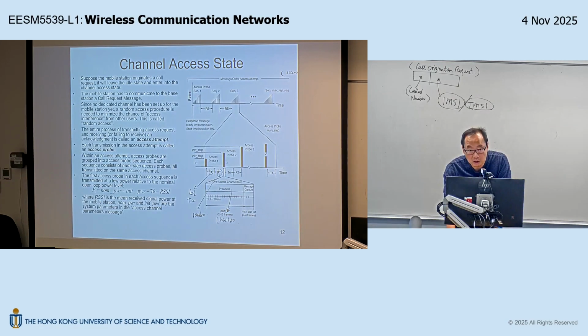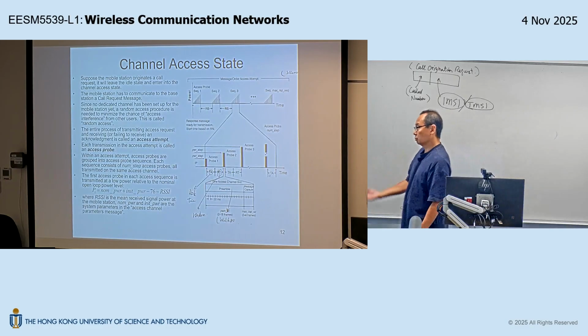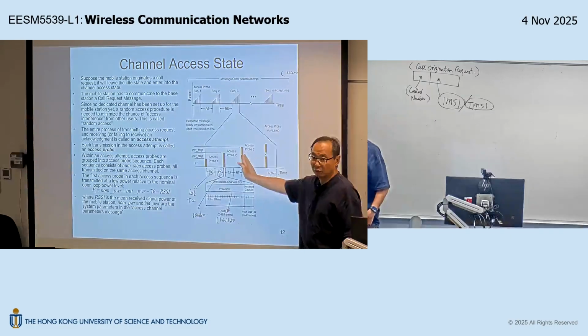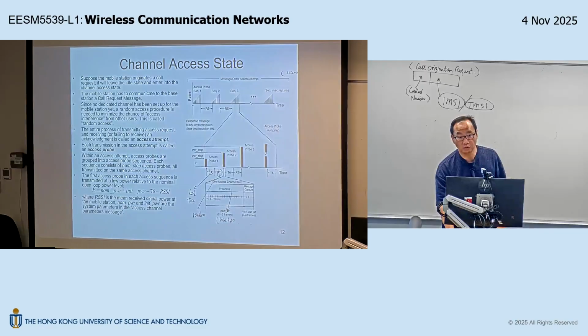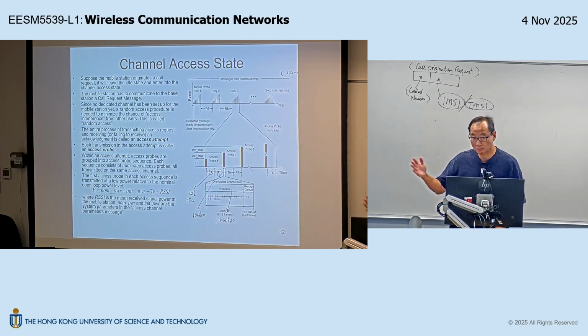On one hand, in between retransmissions, you increase the power, you ramp up the power, in response to the first potential reason of insufficient power. And in addition, you retransmit after a random time, in response to the second potential reason of collision. Okay? So in this way, hopefully one of these attempts will get through, either with sufficient power or with enough attempts that you don't have colliding competitors in one of these future attempts. Is that okay?